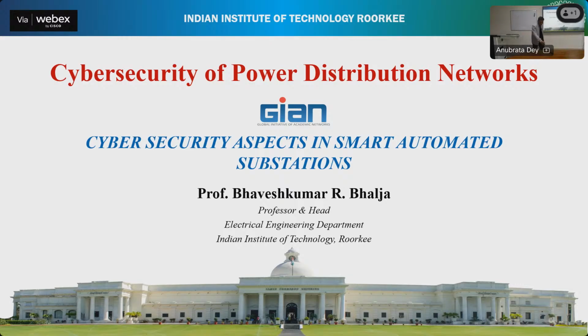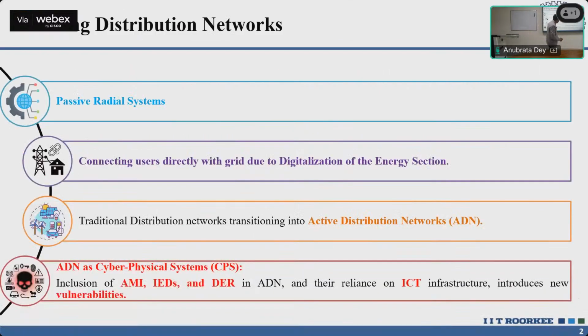Okay, now let us see some aspects related to the distribution network. Right now, from transmission to distribution part, because distribution is entirely different than transmission, because protocols are different. Though some of the discoms are using 61850, still at, let's say, 415 V or lower level, the protocols are entirely different. So if you see our earlier system, that was a radial passive system, radial system.